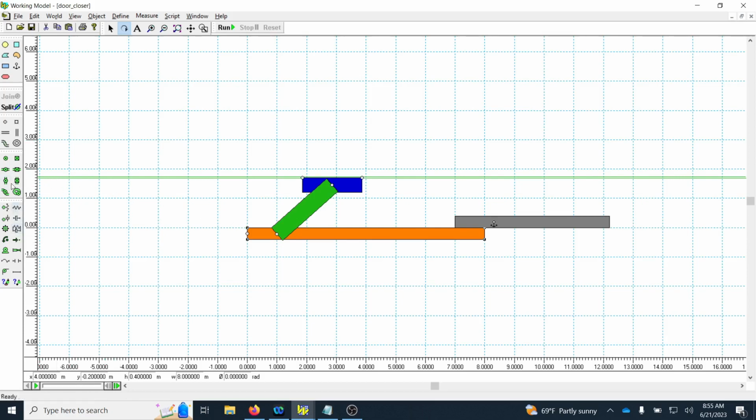So if I look at the left panel, I see a spring damper mechanism right here. If I click on that and select a spring and a damper system, I can create one. When I draw this, the first point I click on is somewhere that snaps on the slider. That means one end of the spring damper is connected to a mass, and then the other end, as long as it doesn't fall on a previously created block, would be on a ground.